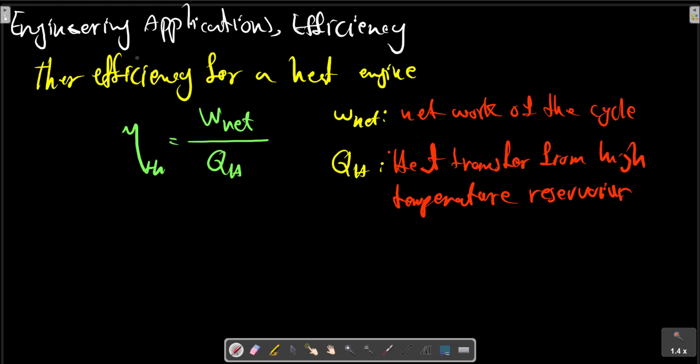In this chapter, we have extended our application of the second law to control volume processes. And in the previous section, we considered several different types of devices for a steady-state process. These include an ideal turbine, compressor, and nozzle. We realized that actual devices of this type are not reversible, but the reversible model may in fact be very useful to compare with and evaluate the real irreversible devices in making engineering calculations.